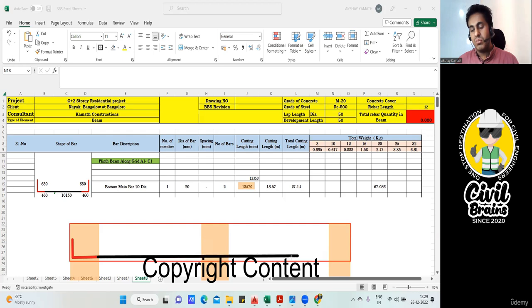Because your bottom you cannot lap at the center. Bottom you have to lap somewhere here, or near the support you can lap. So near the support you can lap in bottom. Yeah, you can lap it. Only in the center you should not lap. I'll bring my bar up to here, or I'll stop my bar up to here. I'll take it to the top, only a bit here.